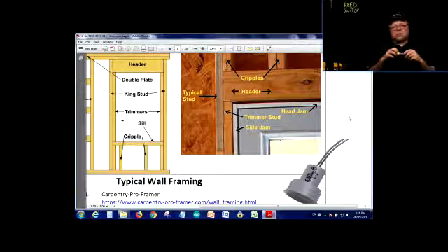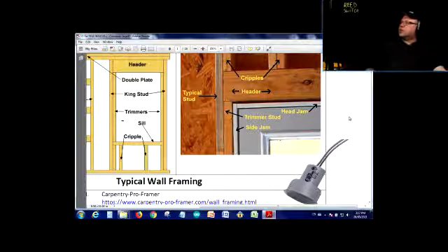They do not need to understand much about wiring, so they might touch your wires and reroute or rearrange them, not in a way that you would like, and then you might run into problems. So just to be on the safe side, wait for them to leave, and then you can route your wires around the air ducts, but before the drywall goes on. Right. So when it comes to this, now this header